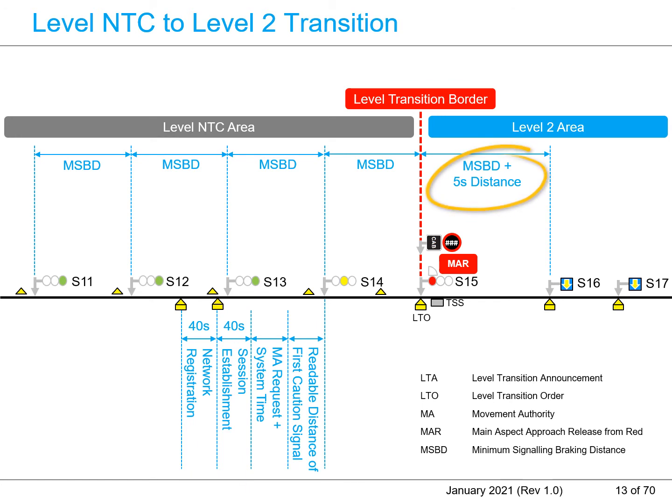When the ETCS on board has not received the acknowledgement action from the train driver via the DMI, the ETCS on board will initiate service brake to stop the train. The service brake will be released upon acknowledgement from the train driver.